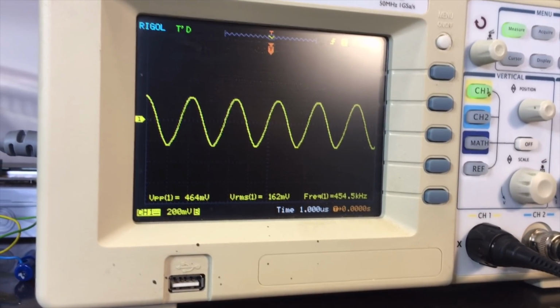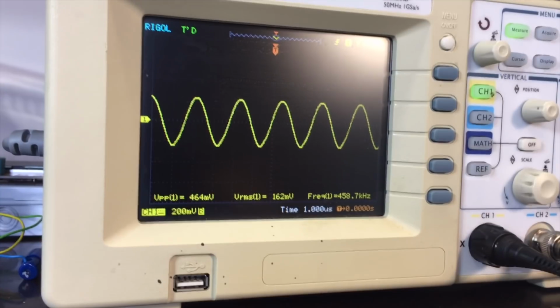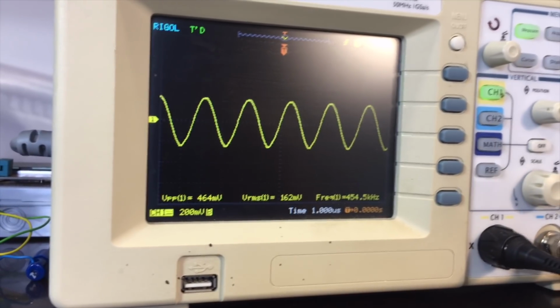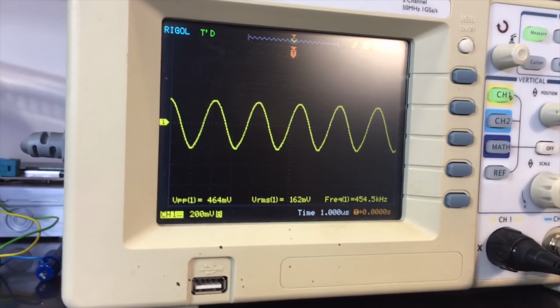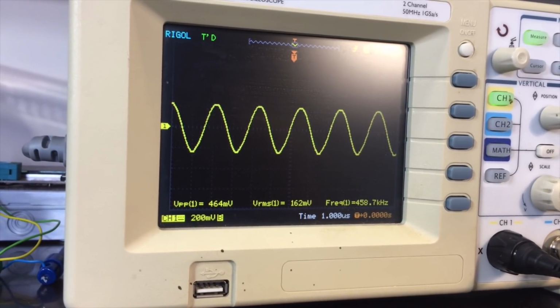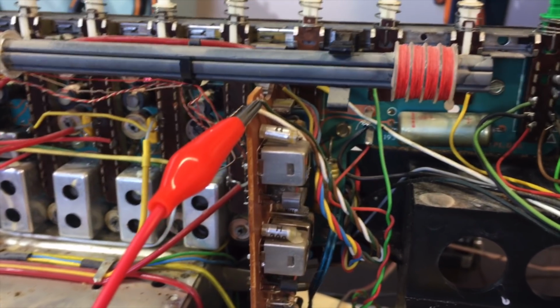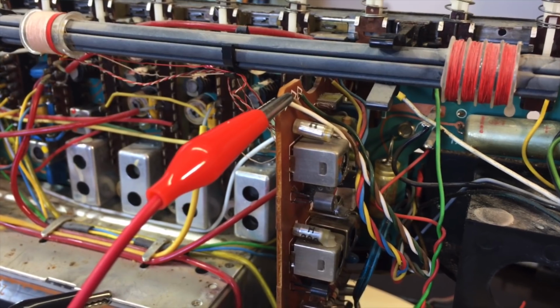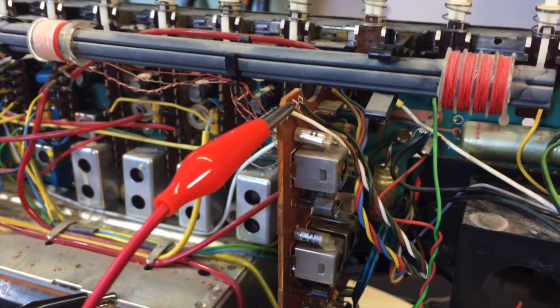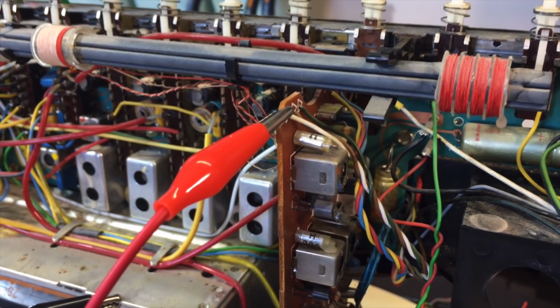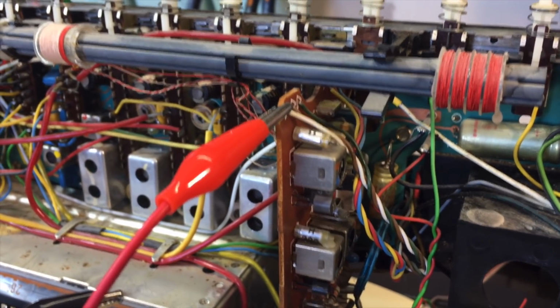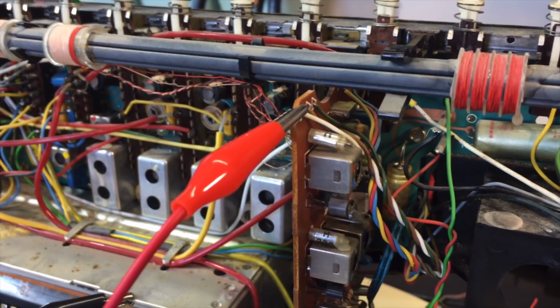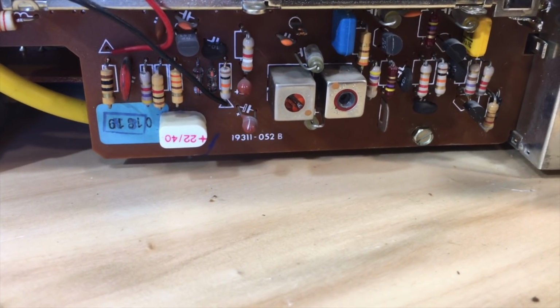So what we're seeing here is a signal going into the front end, the part that I measured the slope to, and this is coming out at the collector of T19. So that's where it's going in there. Basically, it's coming into that section, which is the same as the description we had for the first few filters we had to tune. Now we need to go a bit further back, and I'll go to that point down there and I'll show you what we get on the scope.